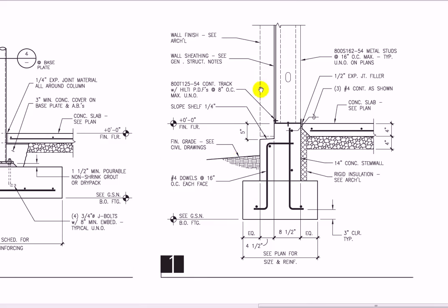Okay, like I said, when we were looking down, this was the outside line and these were the 2 top lines. So what we were looking down, we were cutting through the wall, and we were seeing this little bit of a ledge. The dashed line here indicates that it's the architectural exterior wall, and then here's the indication of the metal studs.